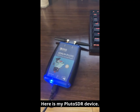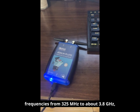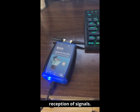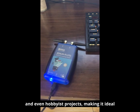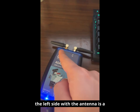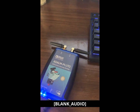Here is my Pluto SDR device. The Pluto SDR device specifically supports frequencies from 325 MHz to about 3.8 GHz, allowing both transmission and reception of signals. It's widely used for education, research, and even hobbyist projects, making it ideal for this demo. As you can see from this device, the one on the left side with the antenna is the transmission side, which transmits the data to the receiver side on the right side.